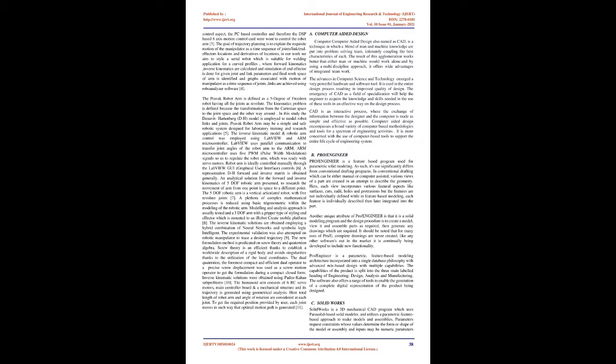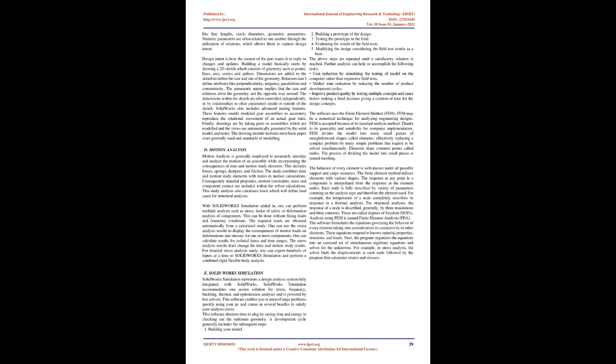The kinematics problem is defined as the transformation from the Cartesian space to the joint space and the other way around. The Denavit-Hartenberg (DH) model of representation is used to design robot links and joints, and during this study both forward and inverse kinematics solutions for this educational manipulator are presented. An effective method is suggested to decrease multiple solutions in inverse kinematics.